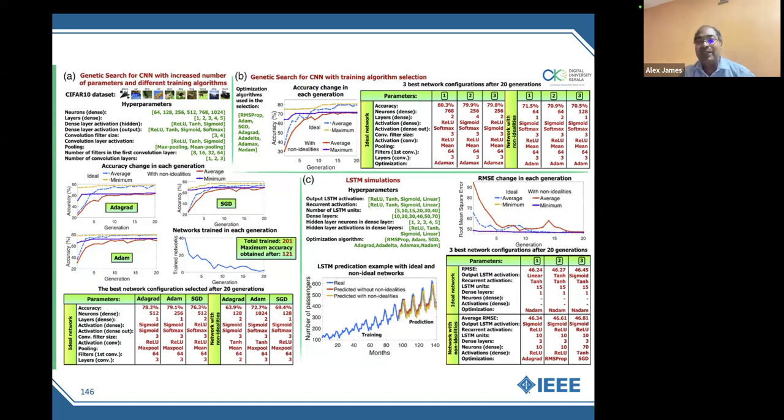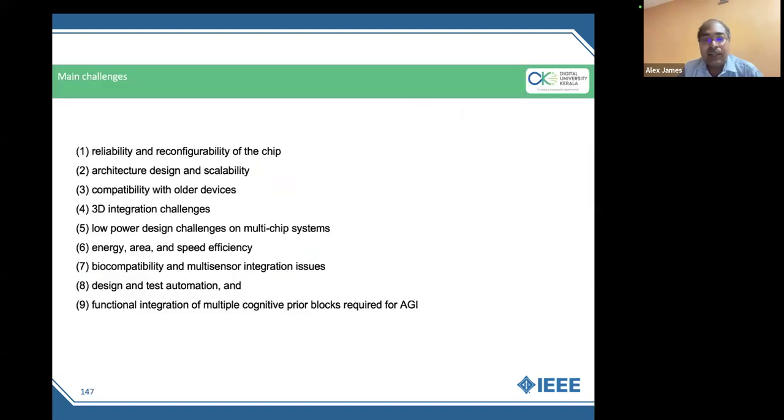So many times we assume we'll just match the exact software-level thing into the hardware. In analog, that doesn't work like that. So basically you need to take whatever the hardware is with you, the cells that are there, and use those to achieve the performance metrics that you want, with aging, with variability, everything taken into account. Then in one case you have ReLU coming as best, in another case it's a sigmoid. Entirely different kinds of circuit blocks come out. So that is the idea there.